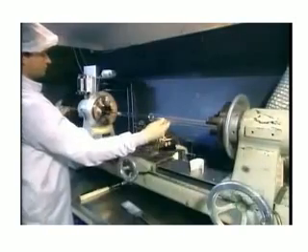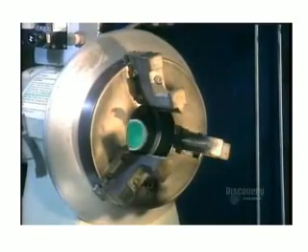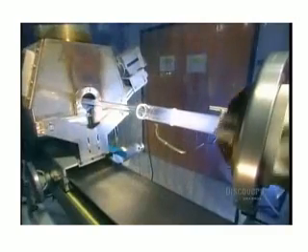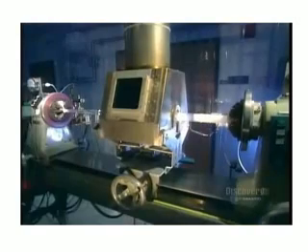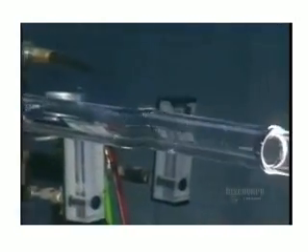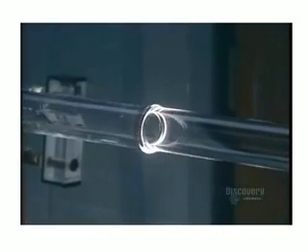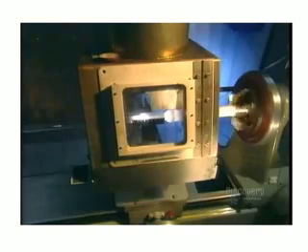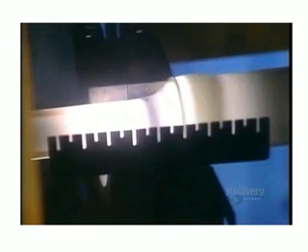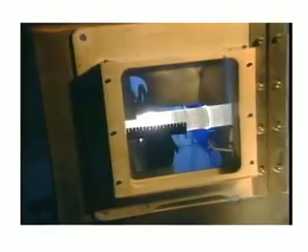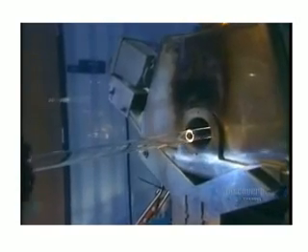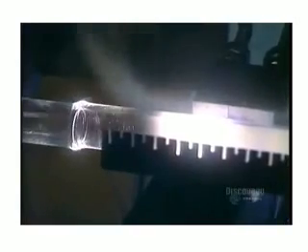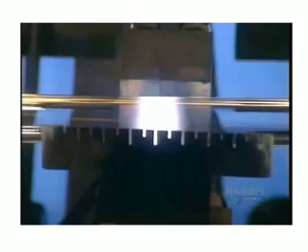They put this new longer tube onto another lathe. As the tube spins, they inject a mixture of chemical gases inside, while a traversing burner heats everything up. The gas mixture contains liquid forms of silicon, an abundant chemical element found in nature, and germanium, a chemical element similar to tin that's used as a semiconductor in transistors and other electronic devices. As the gases heat, they undergo a chemical reaction that leaves a white soot on the inside of the glass tube. The heat fuses the soot, forming what will eventually become the core of the optical fiber.